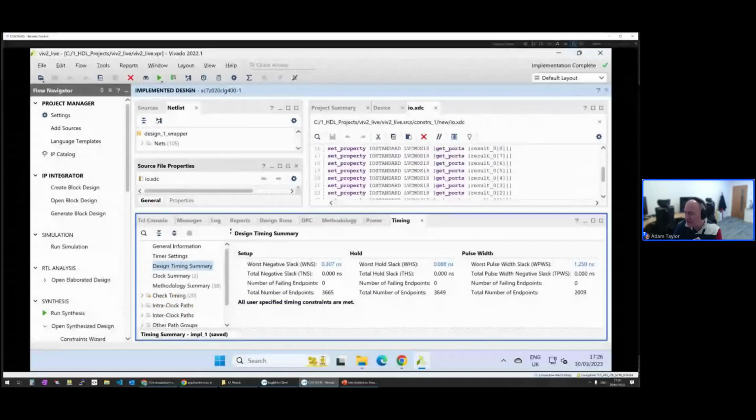So Gareth, I don't think you have to leave the register. I don't think you as the engineer have to compensate for the propagation delay through the block RAM. I think you can just do it for one clock and then it will flow through. It's just the latency on it coming out. So as opposed to it being a 1 clock latency, it will be a 2 clock latency. It'll be 2 clocks after you've asserted that.